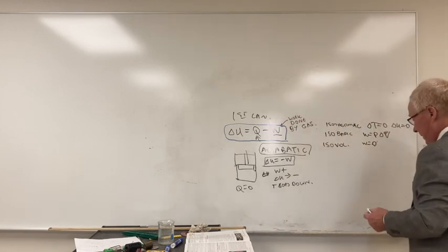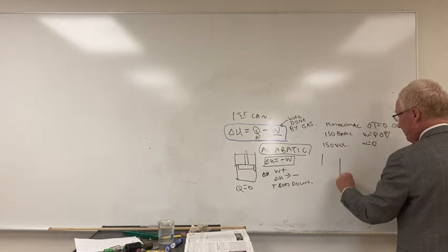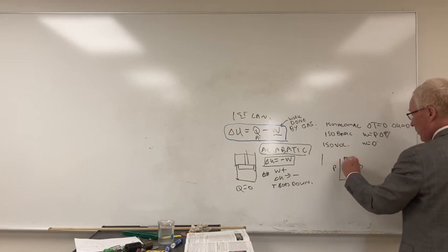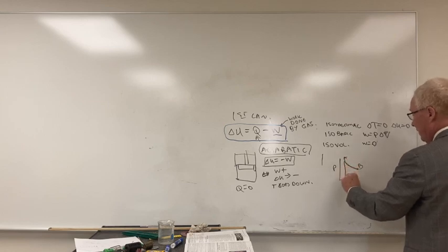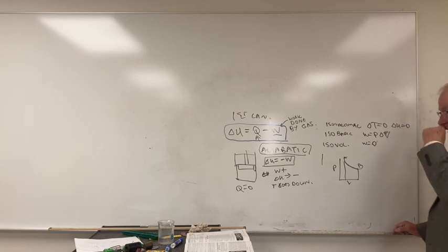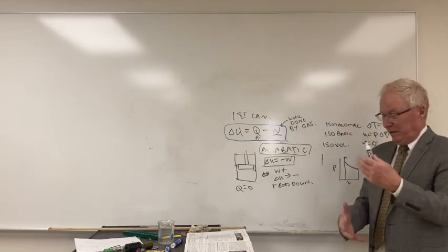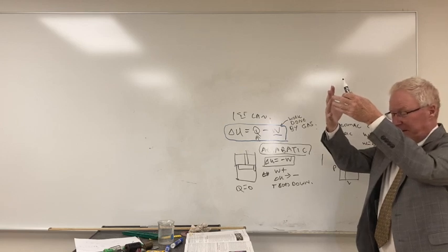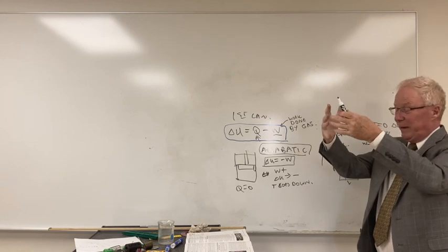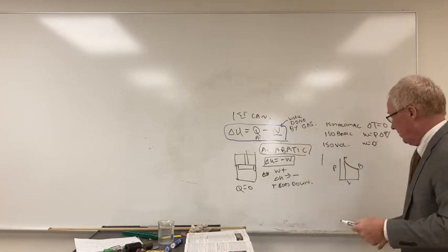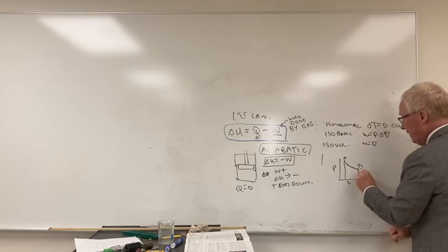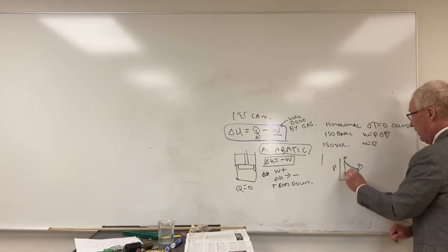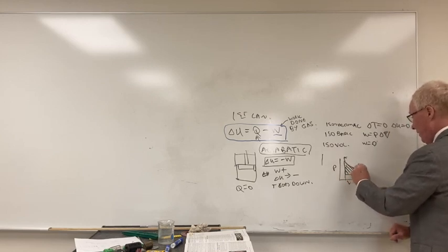I should say one thing, when we talk about this P versus V graph, let's say we go from point A to point B, isothermal, right? That's the work done as the volume expands. Now, in an engine, it goes through a cycle. It closes, gas comes in, explodes, expands. When it expands, the engine takes in more gas, compresses, explodes, and goes through the cycle again. So in this case, if we have a cycle where it comes down, so this is isovolumetric, goes across, and then back up, the actual work done is the area under this part.